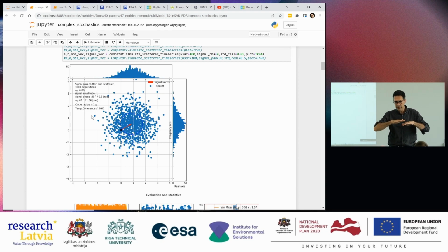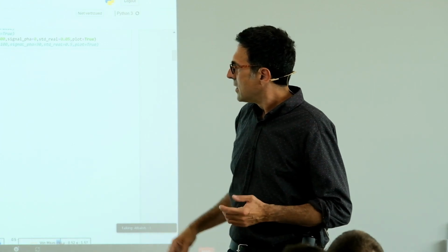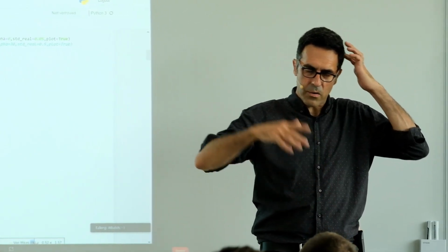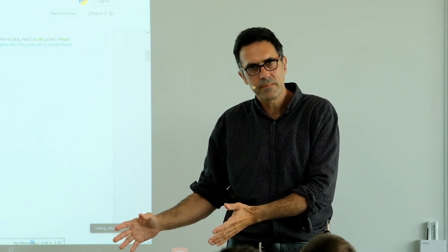The runway of an airfield is asphalt, is flat. I'm looking at that from the side with the radar, so most of the signal goes in, bounces away into space, and I get almost nothing back. That's very good, because if I put something there, then the noise level is very, very low. So the main message is this quality is not something that is only dependent on INSAR or the satellite. It is dependent largely on what is happening on the ground.